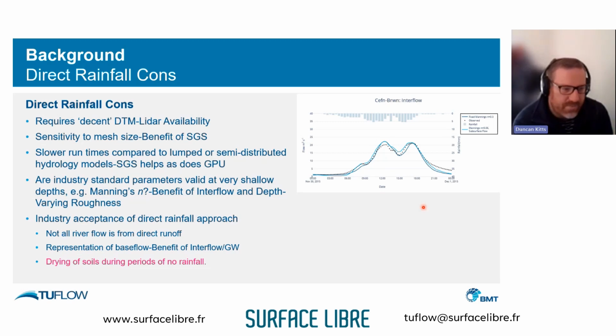So actually we found with turning on subgrid sampling, although you have those sinks, and then like you said, they're leading to essentially depression storage at a catchment scale. By switching on subgrid sampling, we stopped water being trapped in those locations. It could actually find a route out, and we avoided that deeper flow. And actually, that led to a quite significant reduction in the runtime, because we didn't have those deeper flows, and we didn't have the very small time steps associated with that.